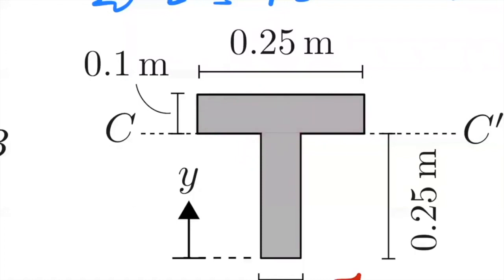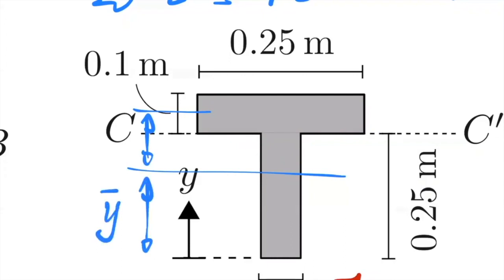And for the area of that thing, by the way, it's relatively simple to calculate the Q. Let's say your neutral axis is here. So you would have this distance from the neutral axis, right? And then you know the area. So it's very easy to calculate the moment of area: it's area times that distance.